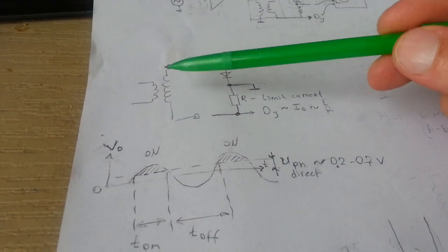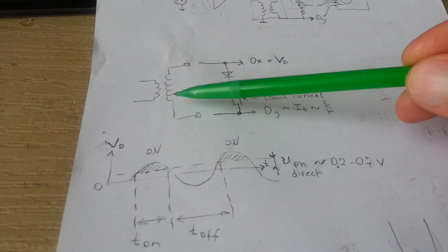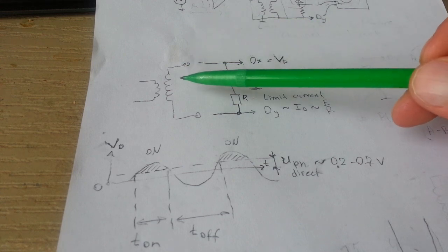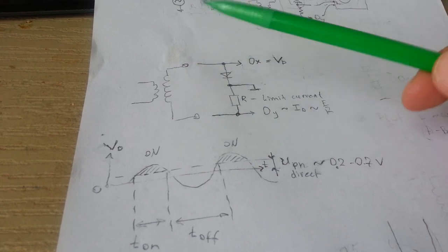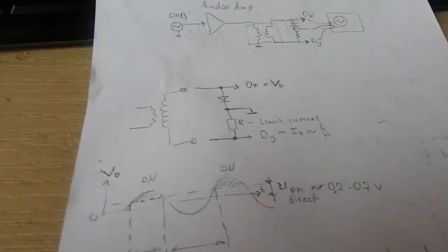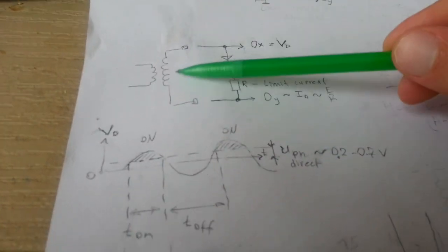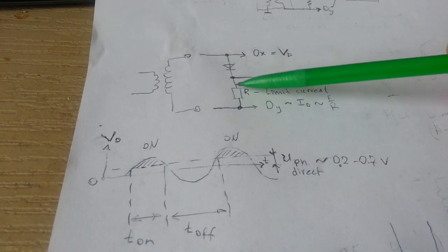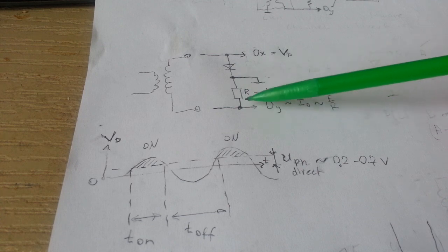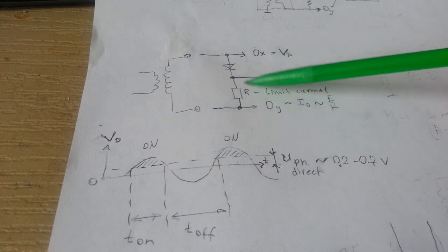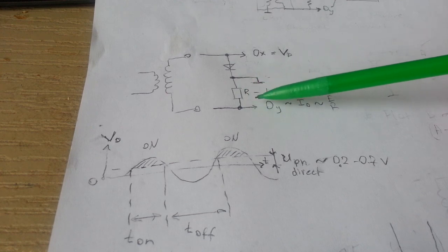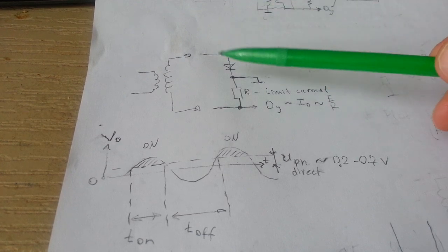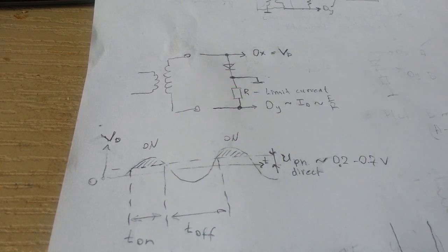So once again, this is the circuit. It's very simple. I expect to have the secondary of this transformer at approximately 5 kilovolts, and I can control this voltage using my audio amplifier. I have the potentiometer to control the signal, so I can control the output voltage. This voltage is applied to the diode connected through the resistor, and the current through this resistor is inversely proportional to the value of this resistor. And as a result, I'm going to see this graph.